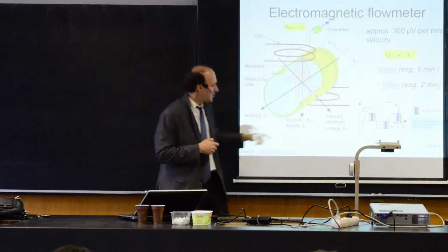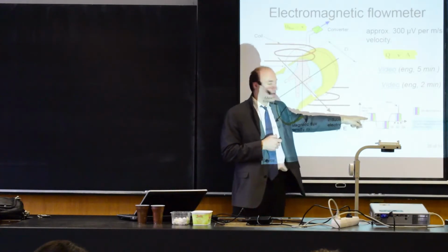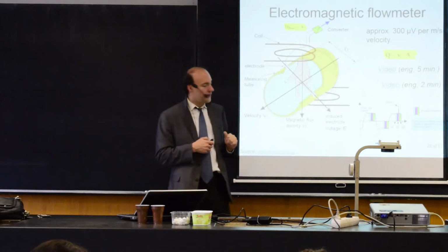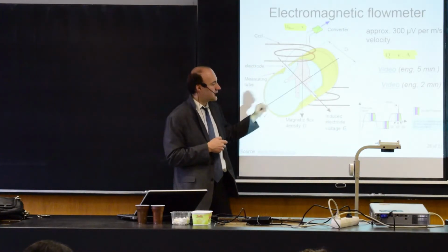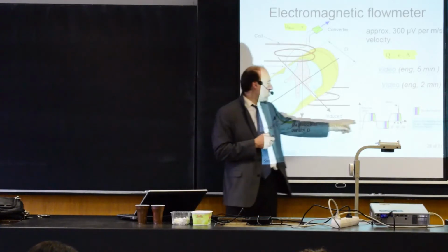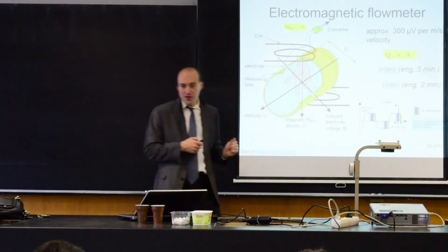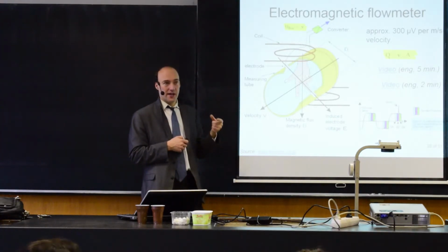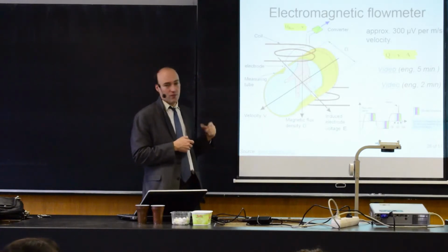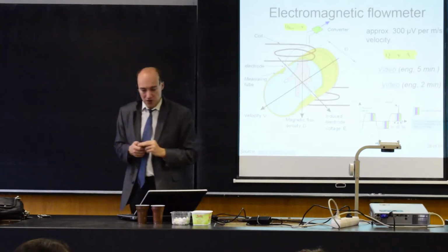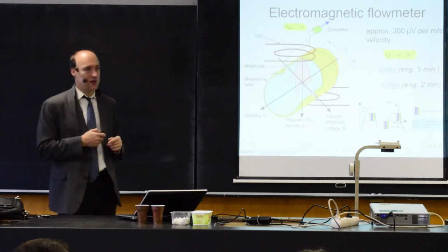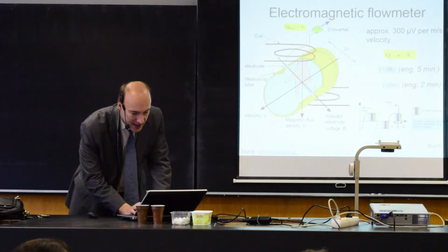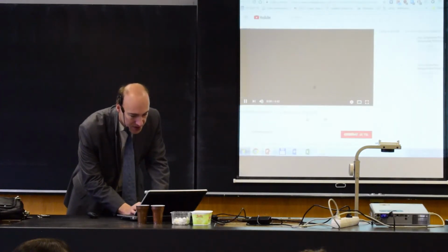And so the signal that you have on the coil typically looks like this. So you apply some positive voltage on the coils. This creates you a magnetic field, and you sample what is the voltage. Then you reverse the polarity. You apply a negative voltage with the same amplitude, and you measure it again. So this allows you to compensate for external magnetic fields, for example. Let's take a look on the video. It again explains how this works.